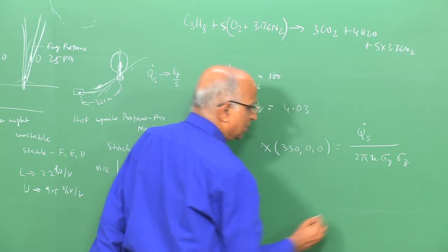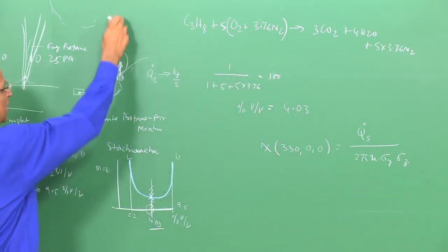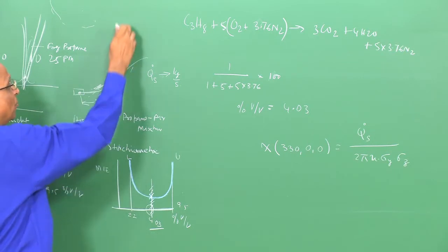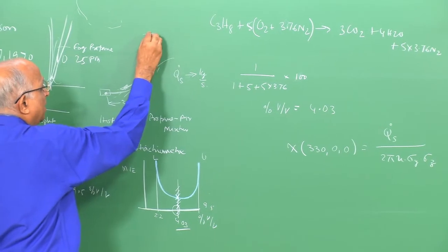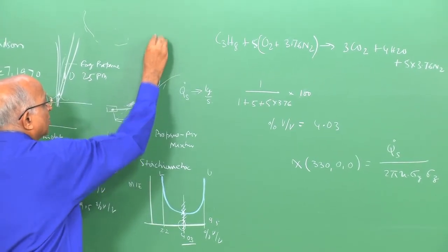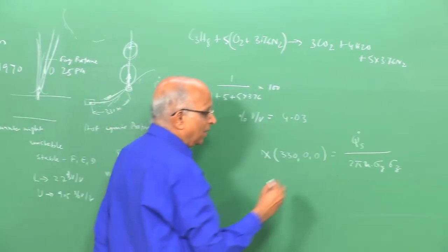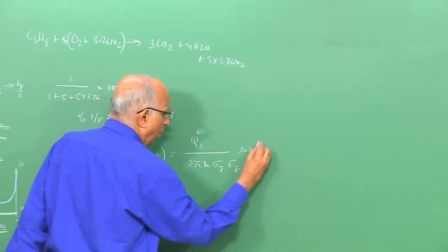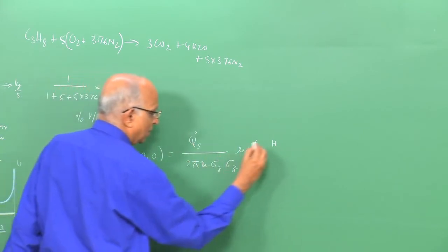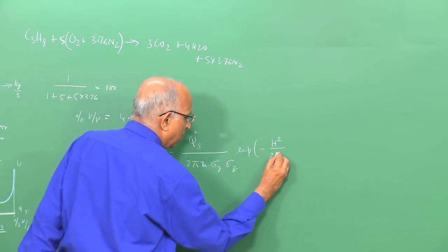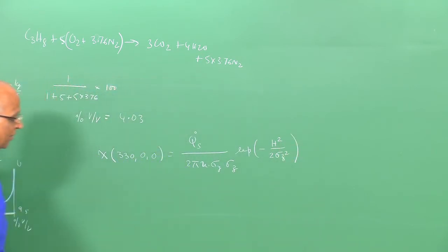dispersion coefficient in the z direction, and if we have a spill of something like, it was between, let us say, 15 to 25 meters, the spill of a particular height, I take the mean height of the spill is something over here from which the gas diffuses out. I say, well, it is equal to exponential of minus the height at which the effective mass gets released, that is h squared, divided by 2 sigma z square. This is the way I get the concentration.